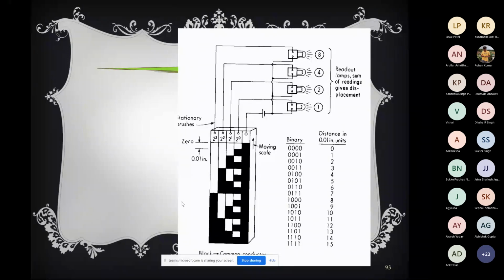The length of this rectangular piece depends on the maximum range you want to measure, and based on the resolution you can divide the tracks. For more resolution you can have 10 tracks, 12 tracks, and so on. Similar to before, you might have the light source and the detector, or if you have conducting parts you can have the battery and connecting circuits, and you can easily construct such a linear optical absolute encoder.